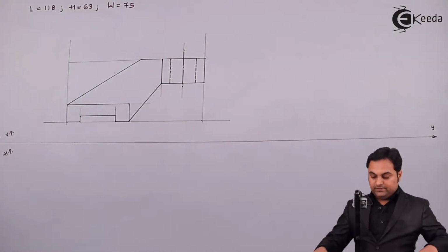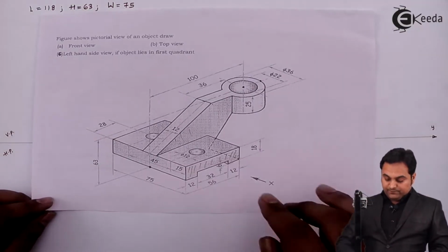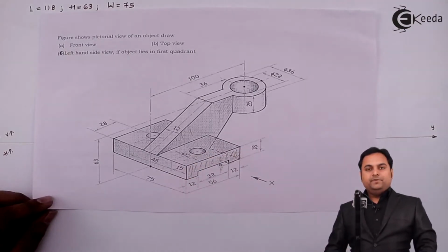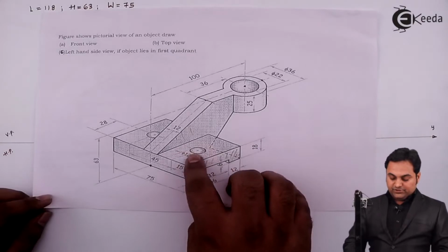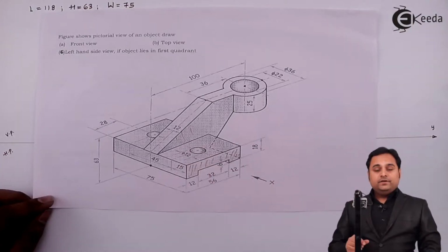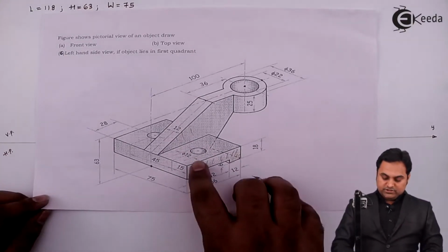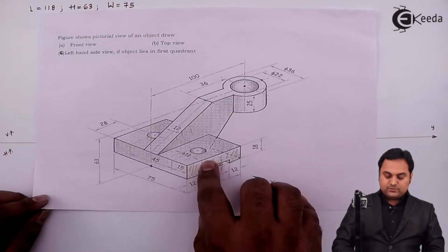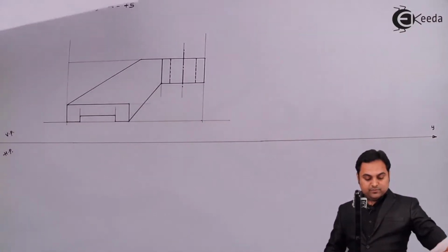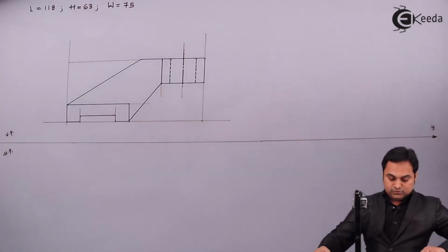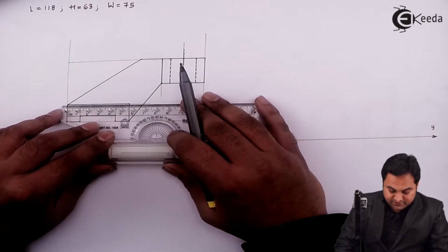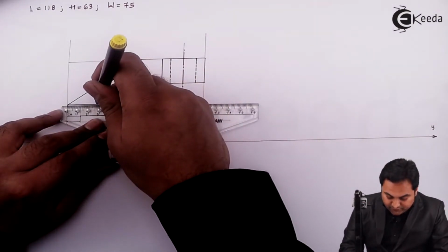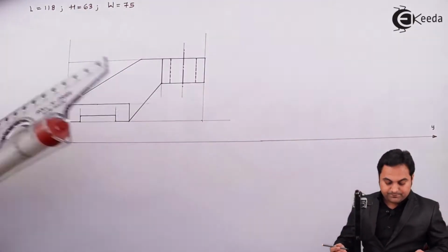Center of the cylinder. Then here we even have a hole inside this plate. That also won't be visible along the x direction, so we need to draw this hole as a hidden rectangle. Now this hole has its center at a distance of 28 mm. Since this complete surface is of 56 length, taking half of that gives 28 mm.